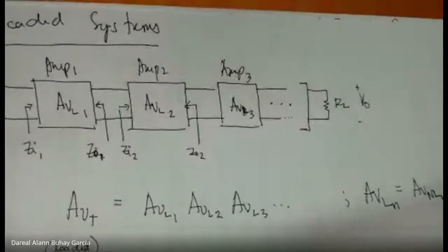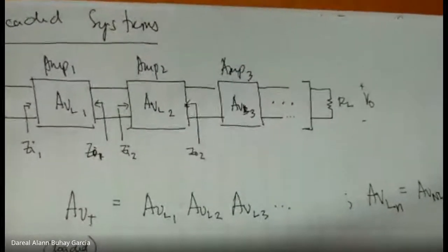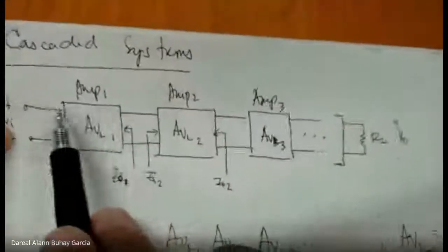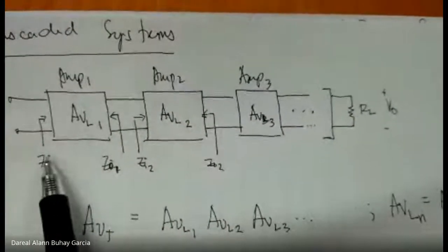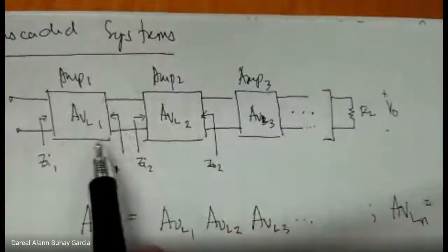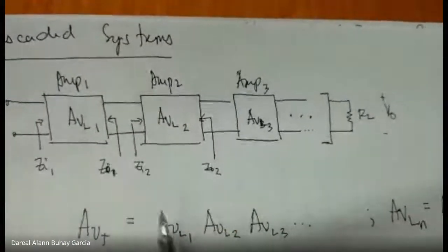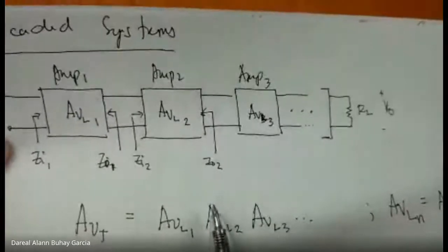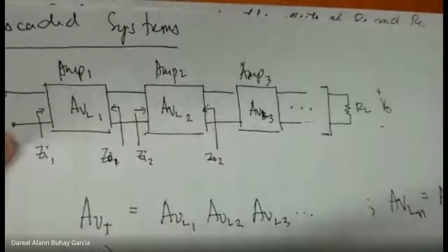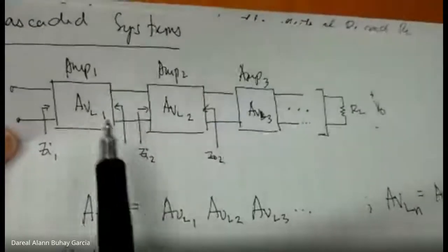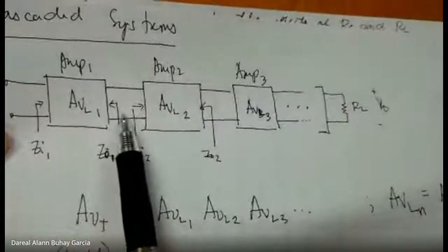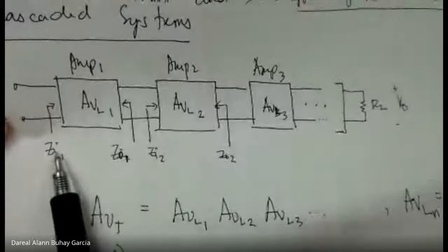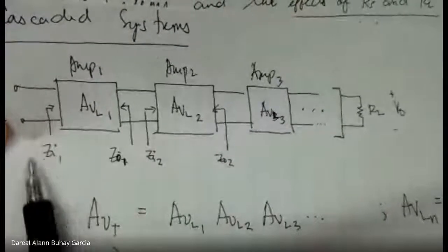Now a bit of trivia: the very first stage of the amplifier should have the largest input impedance. Ideally, for the first stage amplifier, an FET type of amplifier is better because it has a large input impedance, while BJTs are better especially if we want high gain amplifiers. Why is it important that the input impedance be large, at least in the first stage?